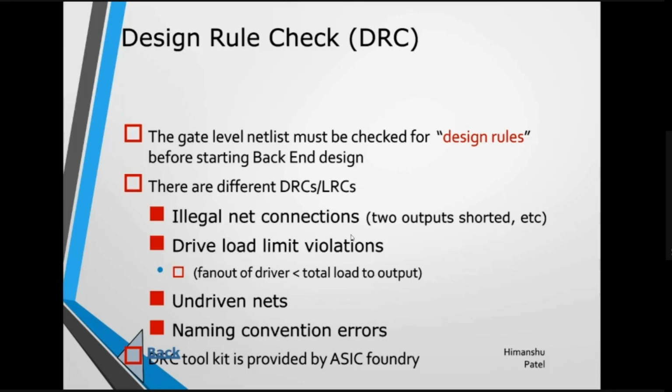You will allocate one register, and for every possible input also you will allocate registers. So the best DFT friendly netlist or RTL or design will be when you have more number of registers, and every register is taking some input or driving some output. So when you do that, your entire design is dependent on the flip flops. These flip flops are controlled by D input, clock, set, reset. Correct? Everybody agree on that?